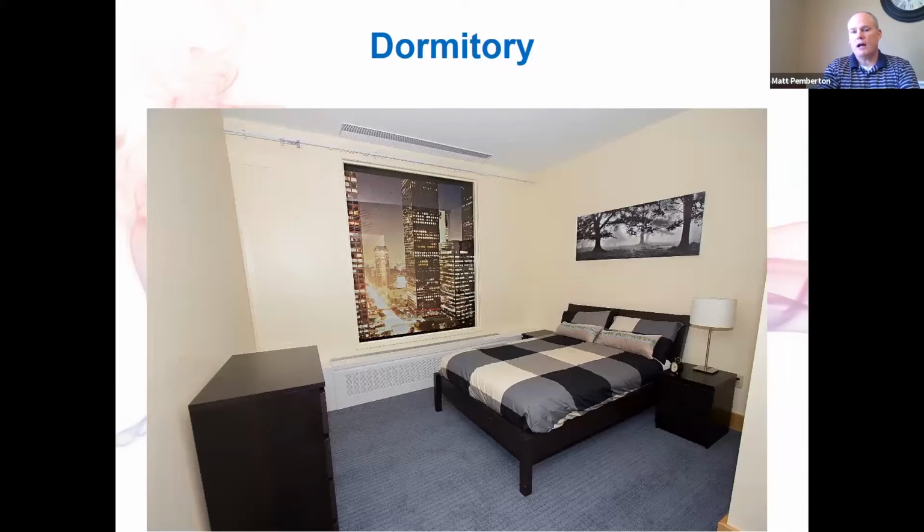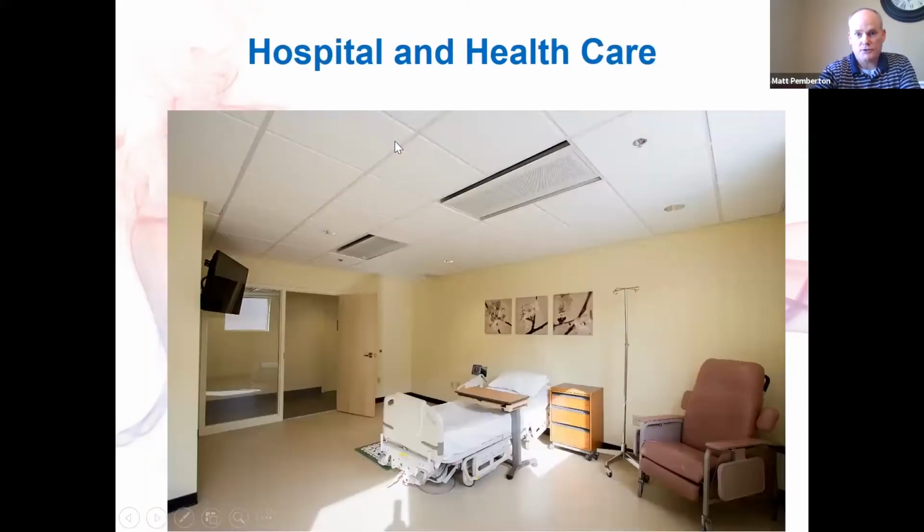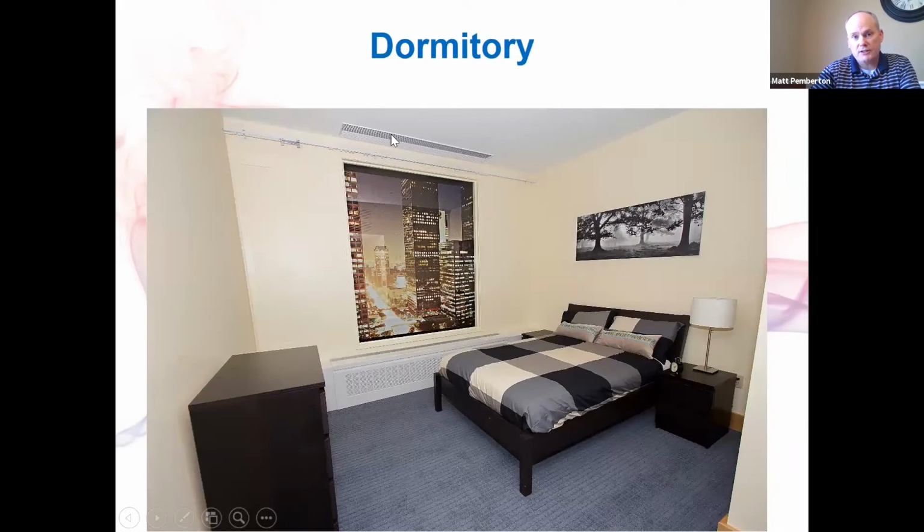Dormitories are single and dual occupancy rooms, another good example of an opportunity to use a chilled beam or hydronic device. You'll see there are two different chilled beams here. There's one in the ceiling, showing you an opportunity, instead of what I had in this screen, where these are 2 feet wide by 2, 4, 6, 8, 10 foot long. Sometimes you have the opportunity to take the chilled beam, turn it vertical, and put it in the plenum. Below, you just have a linear vane diffuser, right? So now you have an 8-inch wide device. It's a different ceiling aspect, with different aesthetics to the ceiling.